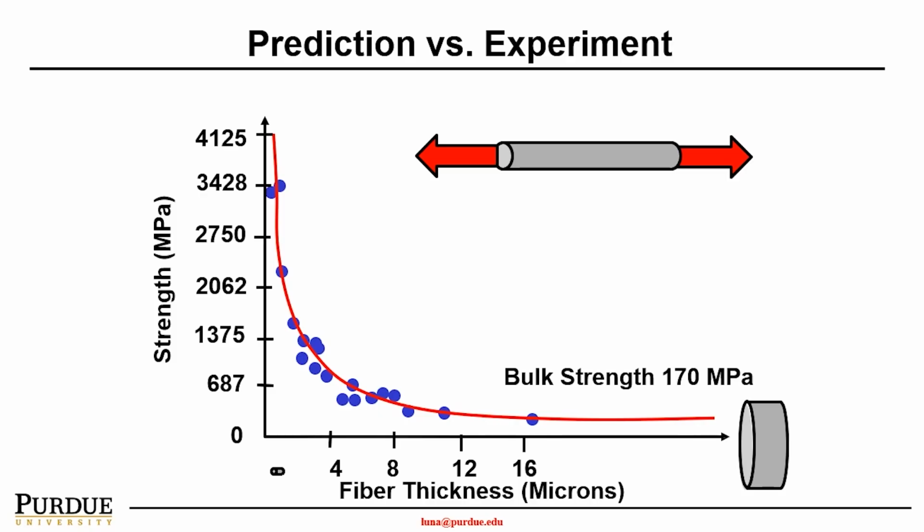The experimental stress needed to break a bulk glass, such as 60 micron or even bigger, is smaller. For instance, for a 60 micron sample, the bulk strength of the glass is 170 megapascal. However, the theoretical stress of the atomic bonds of the glass is about 10,000 megapascal.